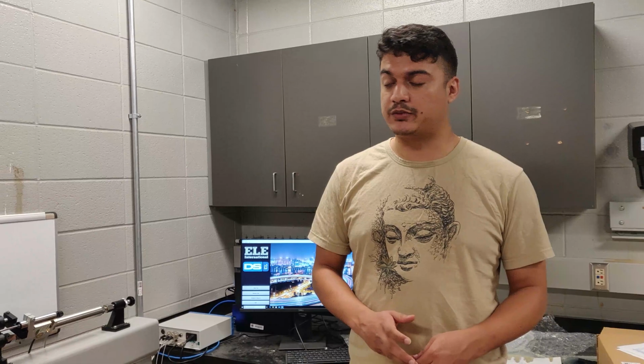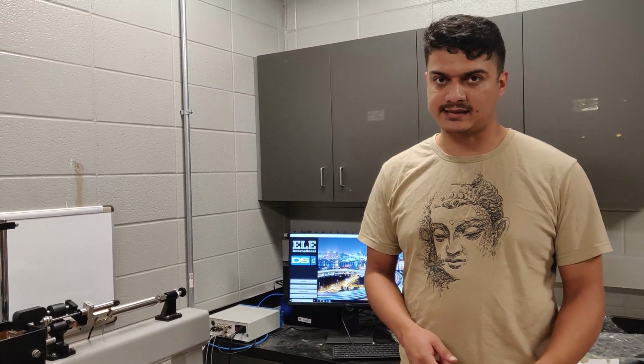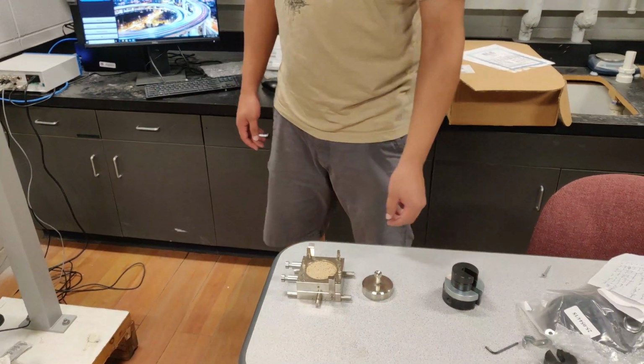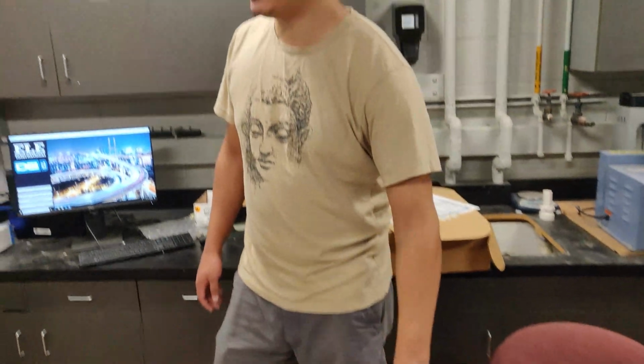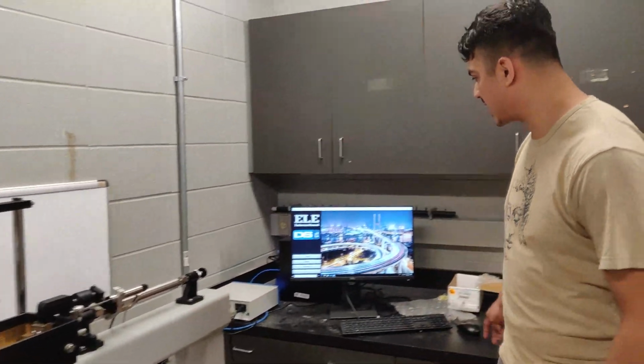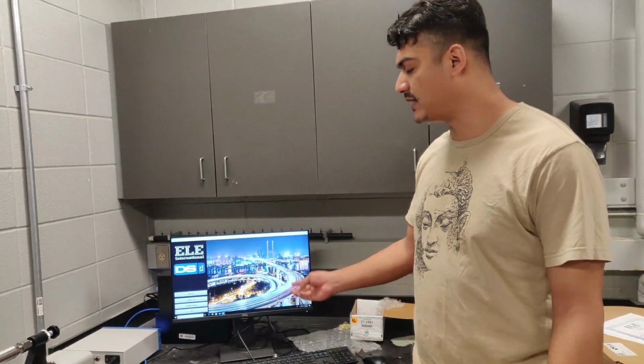Hi everyone, I'm Ratish. Today we're going to see how to perform a direct shear test using a sand sample. We need a shear box with a soil sample and a cap, a load series, a direct shear machine, and the DS7.3 software.